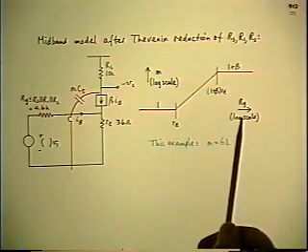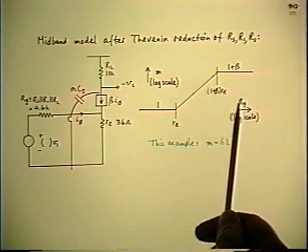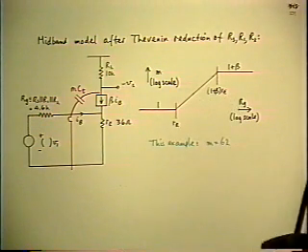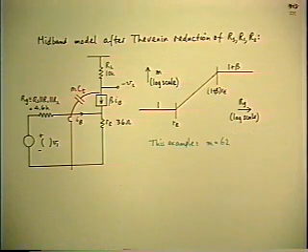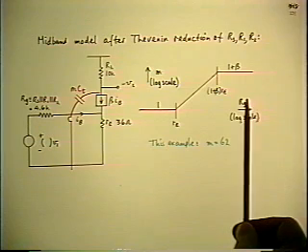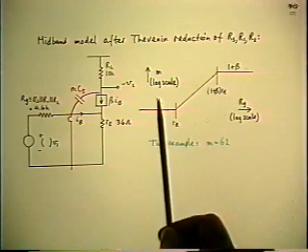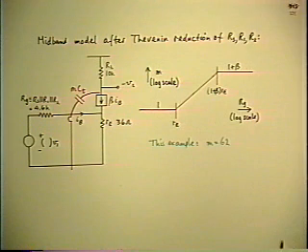Yeah, I think what I'm hearing is you're saying the variable in this case is resistance, not frequency. In other words, the variable is a real variable, while frequency is an imaginary variable, s equals j omega. So when you calculate the magnitude of the frequency response, you take the square root of the sum of the squares, root of 1 plus (j omega) squared. But this is a real function of a real variable. So it's simply 1 over 1 plus 1 at the corner, or 1 over 2, not root 2. So you get a 6 dB corner instead of a 3 dB corner.